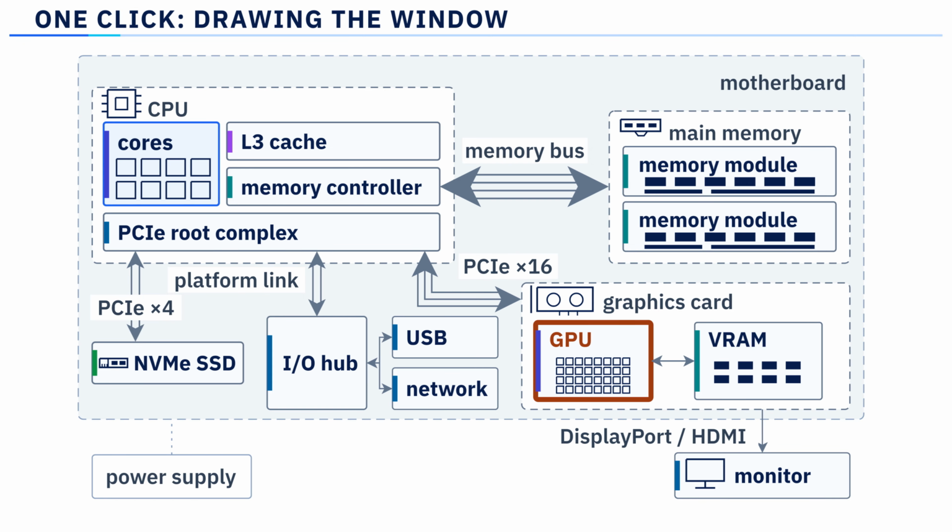Why a processor of its own for this? A GPU is not a faster CPU. It is built for throughput. Many small arithmetic units grouped into compute units, all kept busy at once. That fits drawing pictures. A screen is millions of pixels, and huge numbers of them need the same kind of work. Different groups handle different parts of the frame.